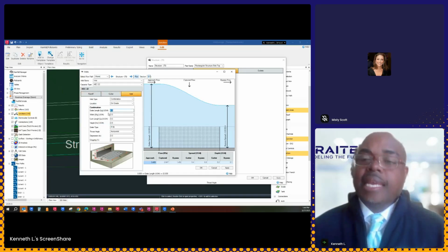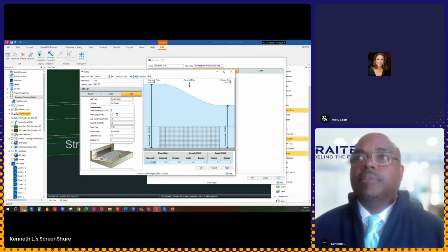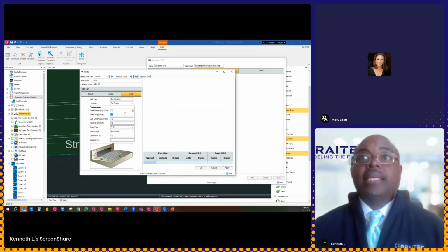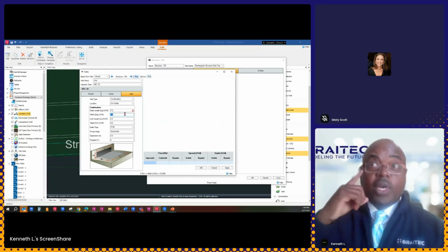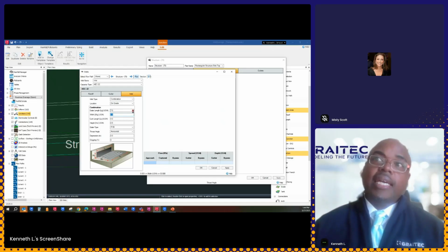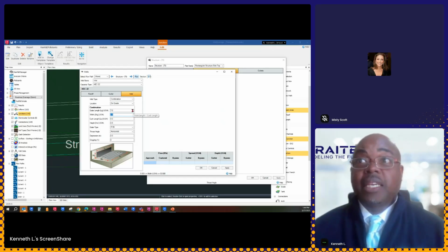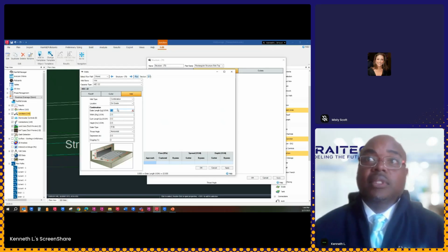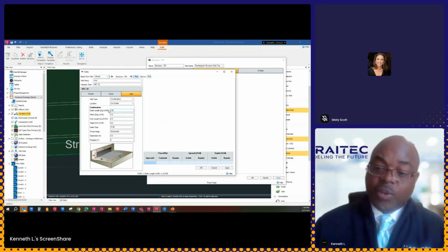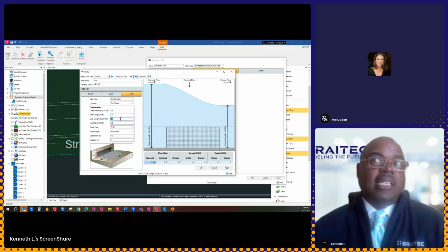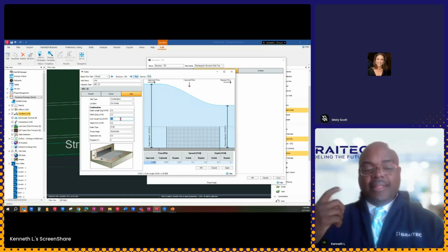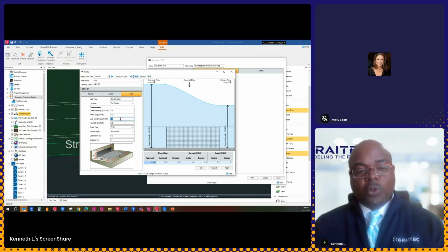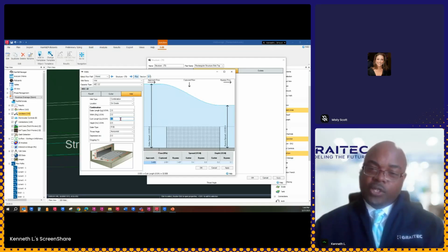As you change these things, let's say we make this 7 feet. When I pick on that, automatically it gives me this little icon. And if I hold my cursor over it, it says grade length can't be greater. So I'll come back. Let's say we want this at 3.5. Oh, wait a minute. This has tools that will specify to you what the issue is and how to resolve it.